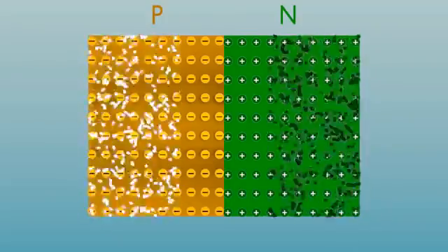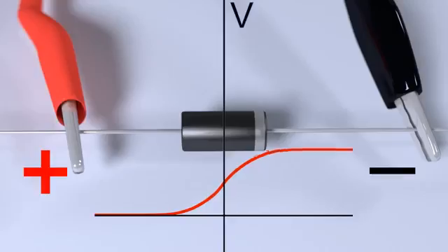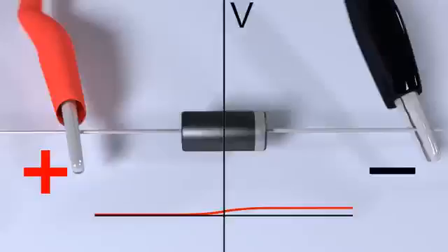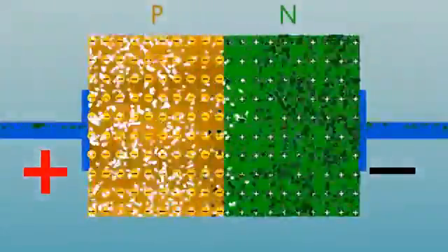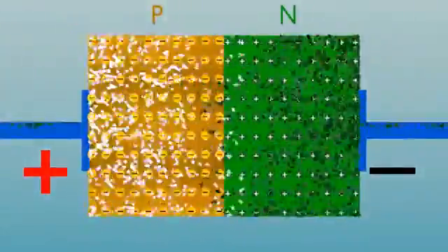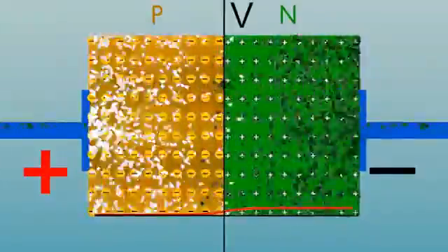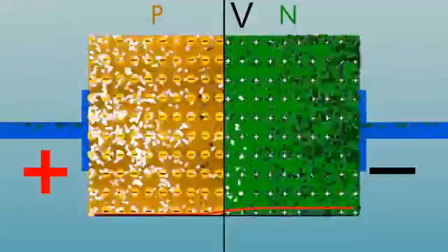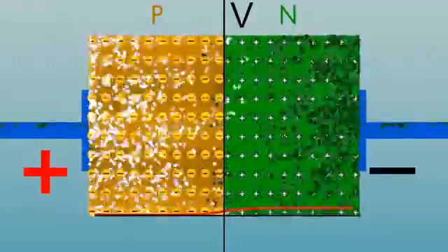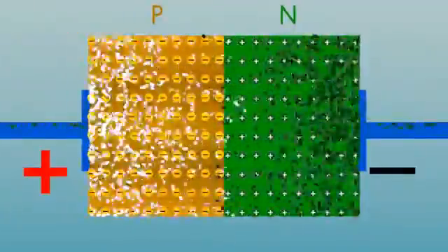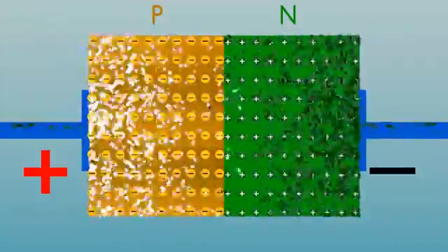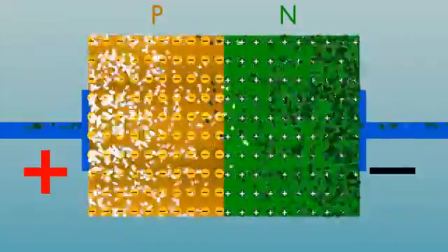By applying an external voltage from a battery, the height of the potential barrier in the junction is modified. If a positive voltage drop is applied between the p and n regions, the barrier height is reduced. A reduced barrier cannot prevent electrons and holes from diffusing across the structure. An electric current appears in the junction due to the diffusion mechanism. Under these conditions, the p-n junction is said to operate under a forward bias.